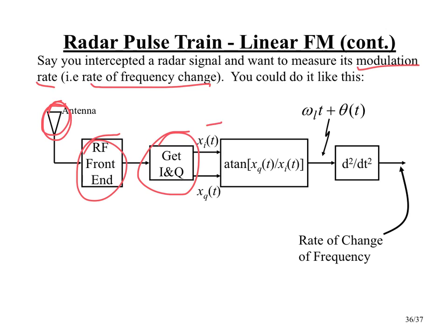But nonetheless, we get our in phase and our quadrature term, and in reality, we would want those as discrete time versions. So if we get this through an analog, we would put in an A to D converter in each of these positions before we do any of the other processing.